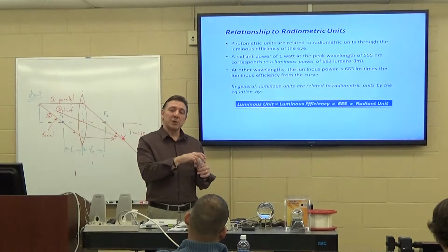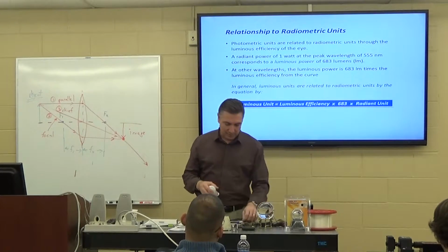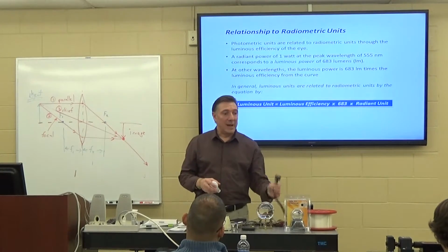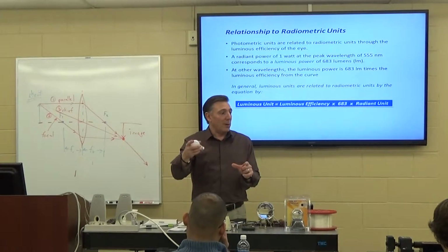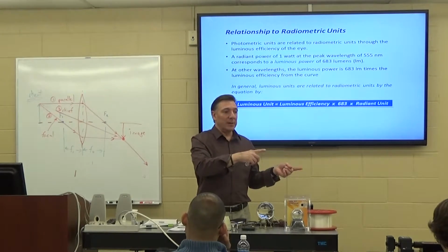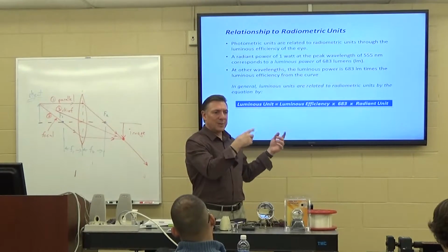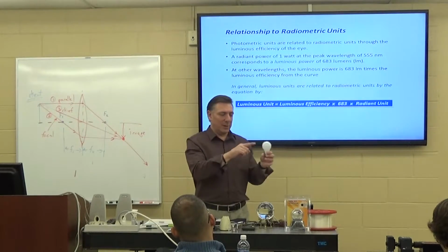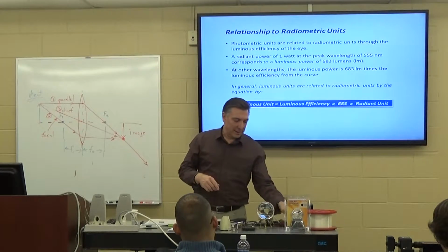If you wanted a measure of the brightness, what you would have to do is measure with a power meter of sorts how much optical radiation is actually coming out of it, what's the optical power, and then convert it to lumens using that chart to figure out actually how bright it is. And we'll get to the measurement of this in a second. Actually, while we're talking, I want you to think about this.